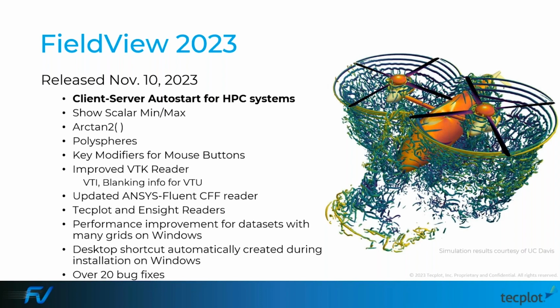We can do separation and reattachment lines as well. We can do surface flows. So they all work in conjunction for showing the features in your flow. And as you mentioned, Shane, you can also do isosurfaces. We provide native variables for doing Q criterion and lambda 2, so you don't even need to code in the formula. They're predefined, and they work great on isosurfaces for showing your strong vortices as well.